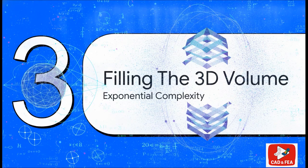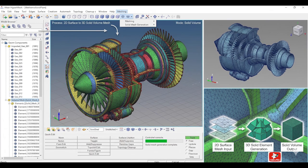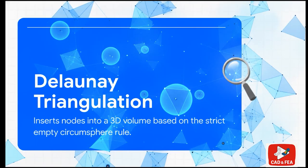All right, let's scale up to our third stage, filling the 3D volume. Going from flat 2D shells to 3D solid volumes introduces an absolutely exponential leap in mathematical complexity. For 3D tetrahedral meshing, the absolute gold standard algorithm is Delaunay triangulation. To build these 3D pyramids, tetrahedra, the algorithm inserts nodes into the volume based on a remarkably strict geometric law called the empty circumsphere rule.